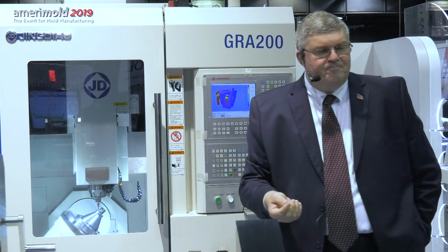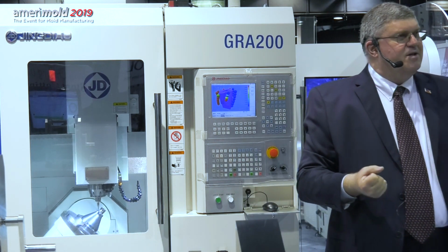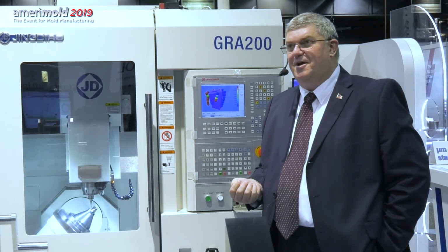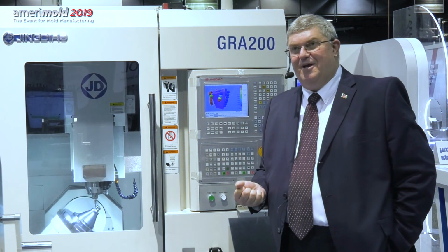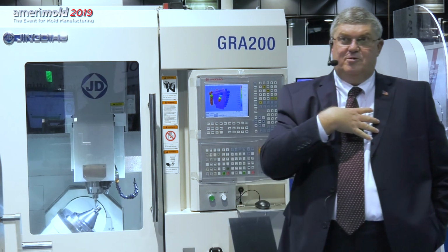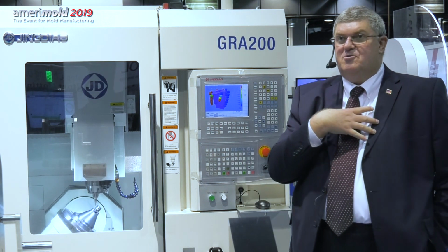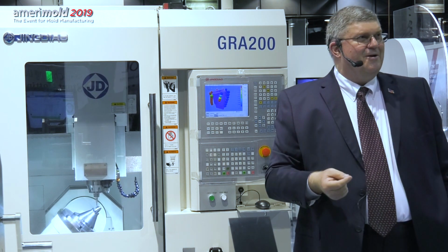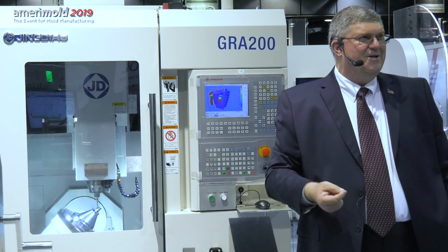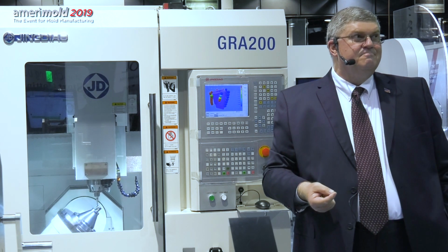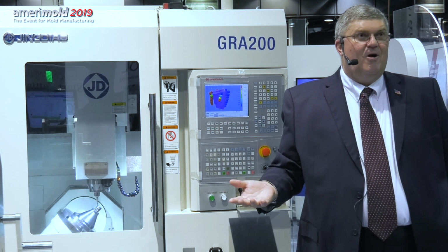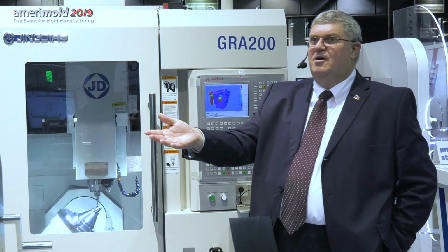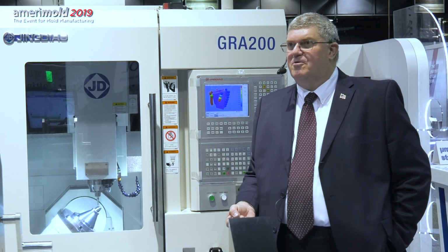On that particular part, we are holding a depth of plus or minus 10 micron, but we have a capability of 133 CPK with a 167 PPK, and we're holding in our shop, which is environmentally controlled, less than plus or minus 2 micron. So when you think about it, plus or minus 2 micron, holding a depth all day long, this is where our advantage is as compared to doing the final fit that you might have to do on your current process or current equipment.